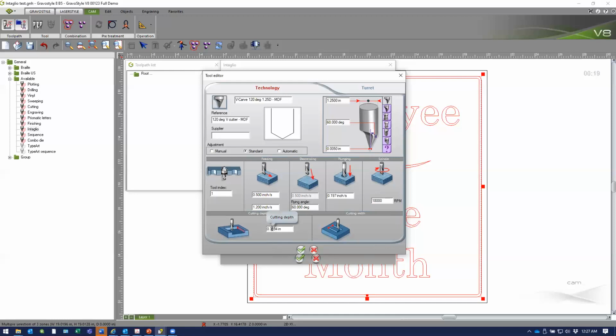Okay. And then the cutting depth. And this goes back to what is the cutting depth, or the flute area of the cutter. How deep can I pierce that cutter in one plunge? How thick a slice of material can I cut away? So in this case, this cutter had a 0.625 cutting depth. And what I'm telling the cutter is, if you need to go deeper than 0.625 into the material, then you need to make multiple tool paths to do that. Okay, and we'll come back to that a bit later.